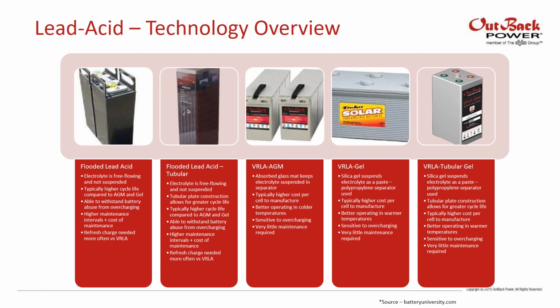Disadvantages: they are comprised of hazardous chemicals, so that sulfuric acid, especially with the flooded batteries, is much easier to spill. If you do spill the sulfuric acid, you need to know the appropriate precautions to take. You need to have the material safety data sheet on hand. You need to have all the right personal protective equipment to deal with that chemical. It is very corrosive and very caustic.